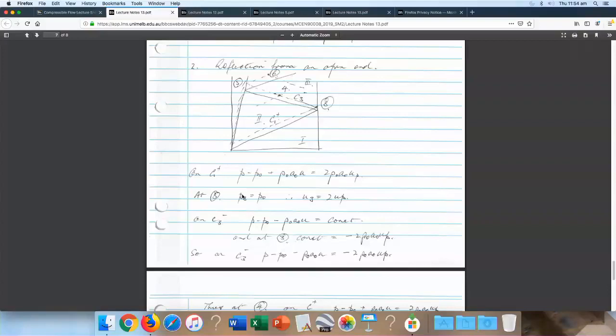But the normal shock gets weakened quickly by the reflected characteristics. As you go around this corner, you have characteristics that weaken the shock. So the shock gets weaker and weaker until you finally get right away, instead of the shock being normal, the weakest shock is when it's at an angle mu to the free stream velocity. So it's a Mach wave, but it doesn't go away.